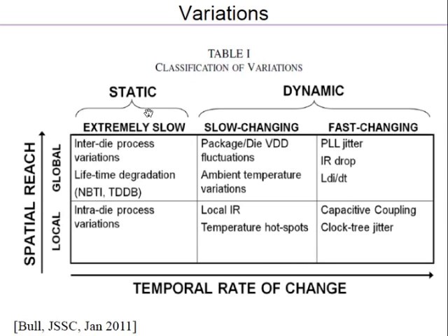Essentially we are talking of variations in the transistor's characteristics. The most important parameter is the threshold voltage, right? Because the gate overdrive above the threshold determines the drive current, which determines the speed, and the threshold voltage also determines the leakage when it's off. So the threshold is the most important parameter, and the threshold voltage itself depends on many other parameters.